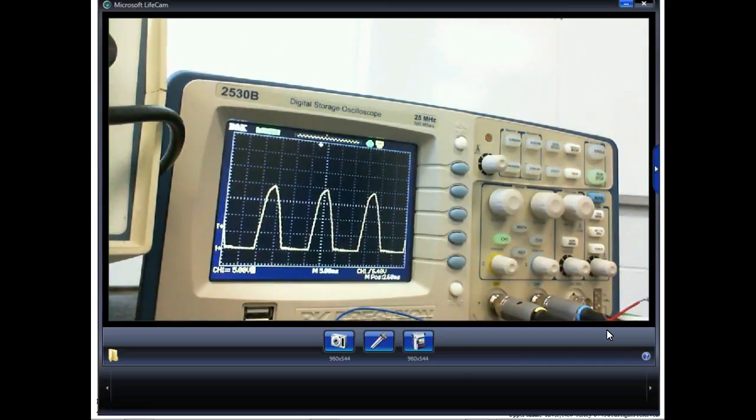We calculated 17.1, but we're getting 20. And why? Well, we don't have 110 volts on the transformer, but using 110 volts, what the transformer's rated at was still close enough for us to get what we need. Everybody understand that? And you can go to your house. Are you going to measure 120 volts at your house? No. It depends on where you're at and how far you're away from the transformer, what tap they use. They've only got so many taps on that transformer up there.